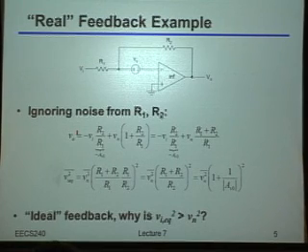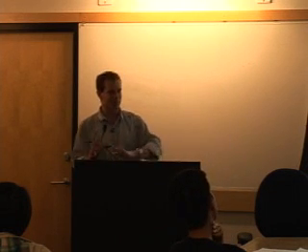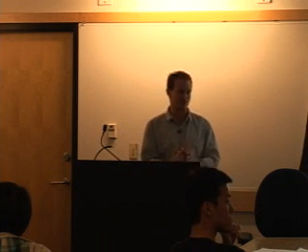Okay. So, first, I'm guessing you mean total integrated noise as opposed to spot noise? Yes, so the question was on question number 4, to give the total input referred noise of the common source amplifier. I believe this is the one with the PMOS load. So you asked if we were doing integrated noise versus the spot noise. Turns out it's actually not going to matter too much. But yes, if you'd like to treat it as integrated noise, that's fine. Actually, just to make life easier, just do it as spot noise and ignore any capacitance at the output for now. That'll be the most clear answer in terms of what we're looking for.